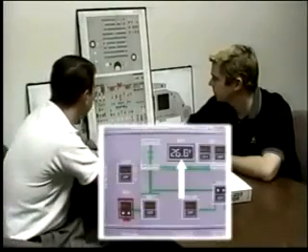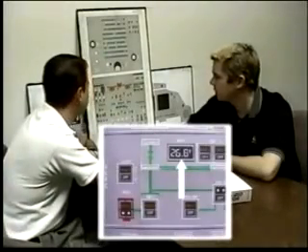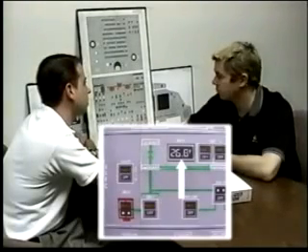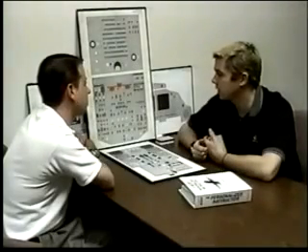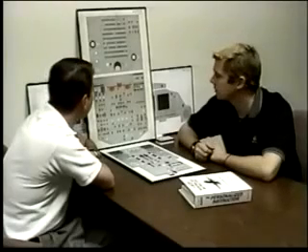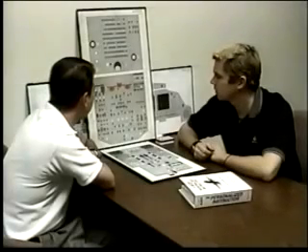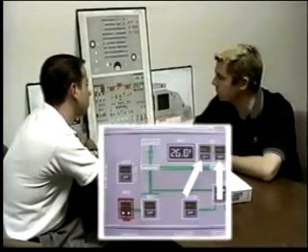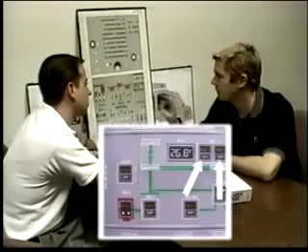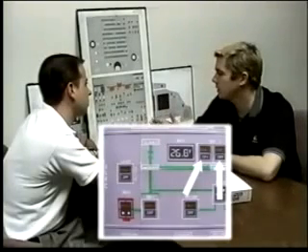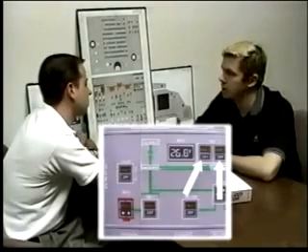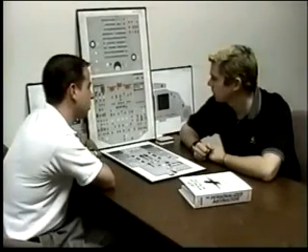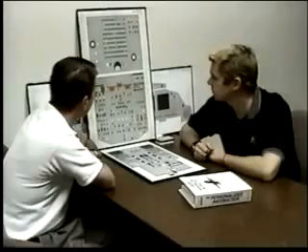Batteries. What is our minimum battery voltage? Min battery voltage 25 volts. However, if it's 22 volts or less for more than a second, the batteries will disconnect. Is there any tests that the crew might perform for the batteries? Yeah, the captain is going to select the batteries off, look on the electrical page, and then select the batteries back on. He's going to check to see that the amperage is 60 amps or less, and it's decreasing within 10 seconds. What about fault in the battery switch? It's just an abnormal charging rate.